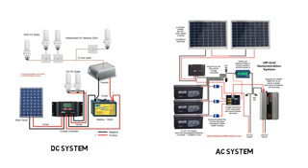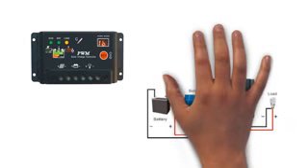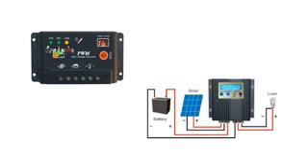There's another important element called the charge controller, as can be seen in the circuit diagram. A charge controller is important to battery health. It should be noted that battery life can be reduced if it's overcharged or when it's utilized if the charge is low. So if the battery is overcharged or undercharged, it loses life.